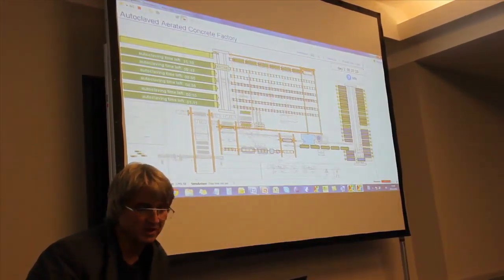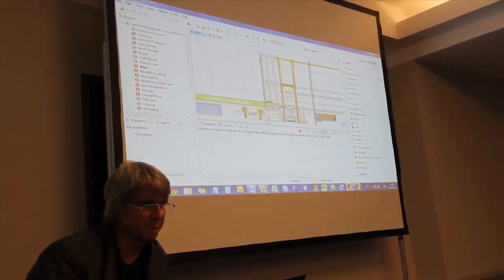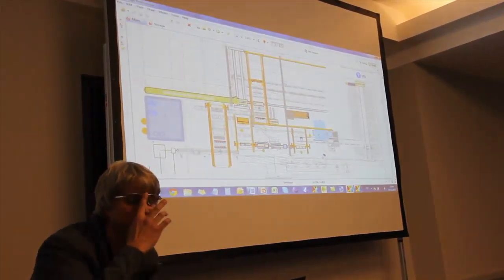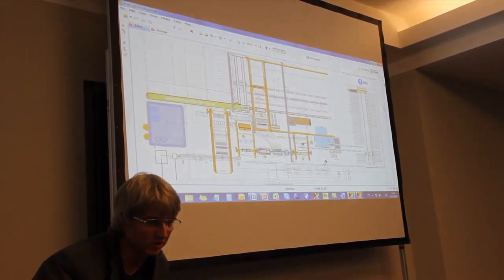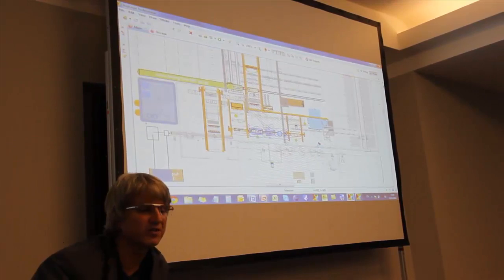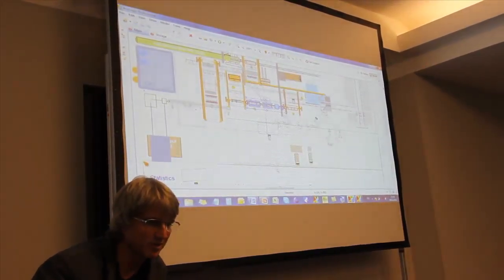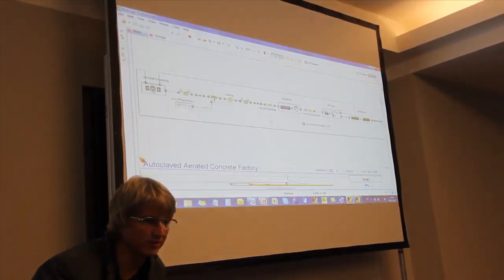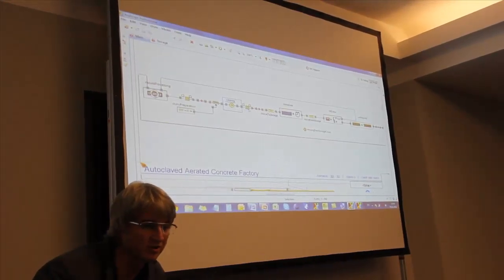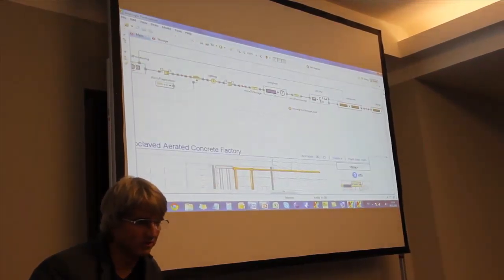While it's being executed, I'll just show you one thing. Typically for problems like that, somebody gives you the factory floor and displays where is what. So the modeler would mark up the space on top of the factory floor with markup elements, and then bind those elements with the delays and queue blocks, so that the animation is available.